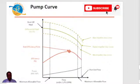As you can see here, if the best efficiency point is here, now if your flow is at say 20 cubic meter per hour, somewhere around here, if you are considering the rated impeller diameter curve, your head will be here. But if you have a maximum impeller diameter curve, you see that your differential head will be here. So you will see the effect of change of impeller diameter.